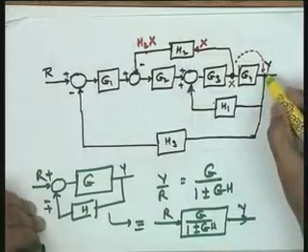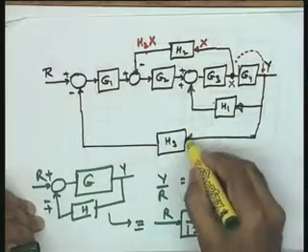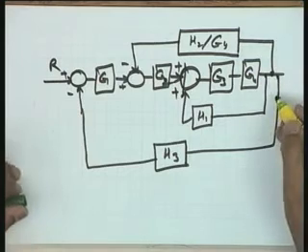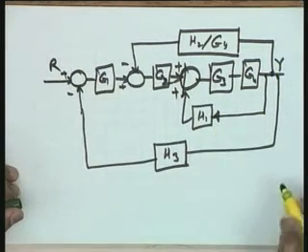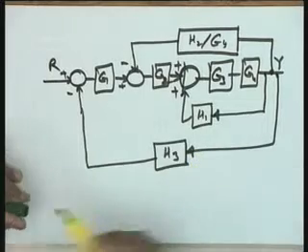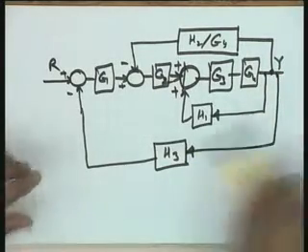Look at this particular point, the Y signal is being fed back through this particular loop as well as through this particular loop. You will not mind if I change this to this form. After all, this signal is Y, this is going as an input to this particular block, this is going as input to this particular block. So, I have simply separated out the takeoff point.